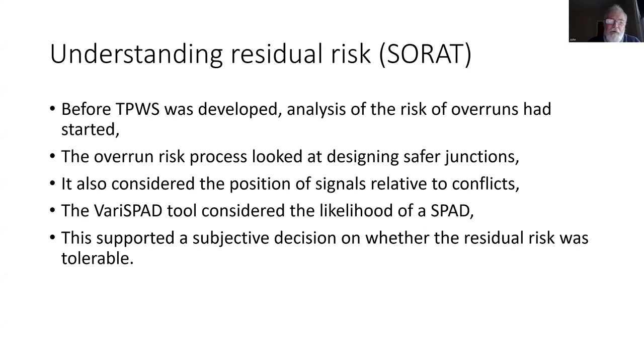A tool called the VariSPAD tool allowed the operators and designers to consider the likelihood of a SPAD, taking each signal individually, looking at how often it might be at red or green, where it was, whether there were sighting issues, how long the overlap was, other distractions on the approach, and so on. And that supported a subjective decision process on whether the residual risk was tolerable.